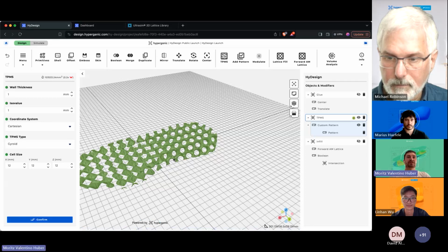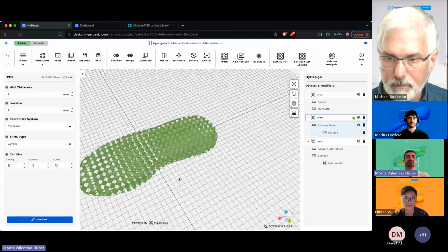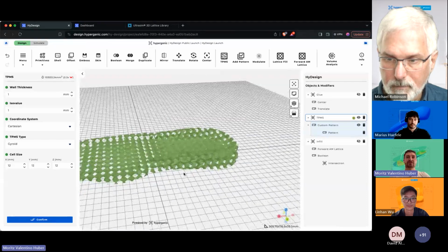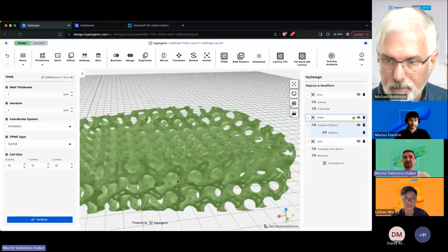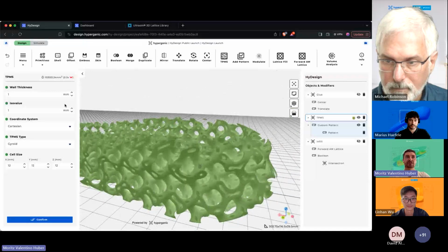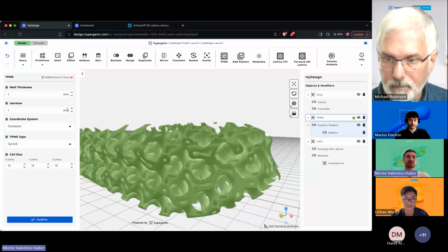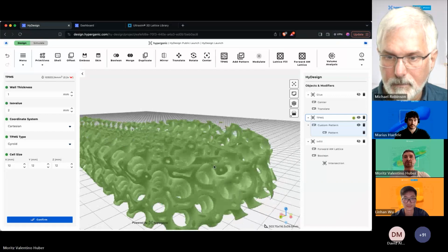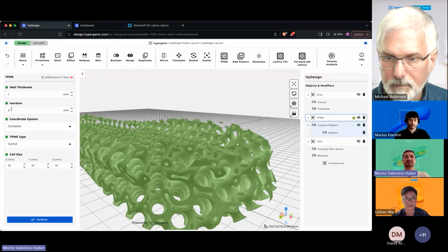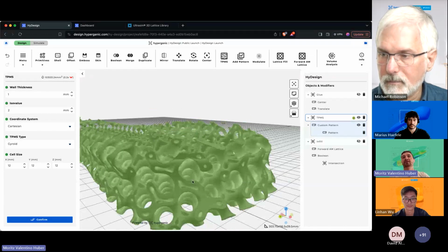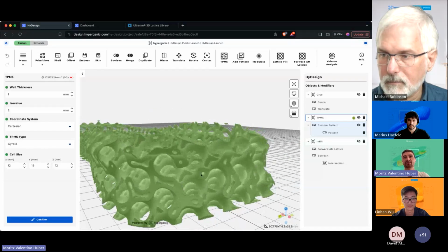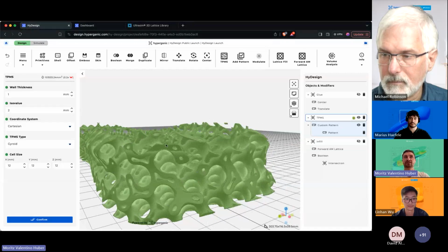Let's have this calculate for a second and wait for the rendering to update. So now you see that in this case here, the gyroids, you're closing off the channels, the further you increase this value here. So through the setting of an ISO value, you will be able to control if your entire structure is a sheet-based or a solid gyroid. Of course, any type of TPMS.